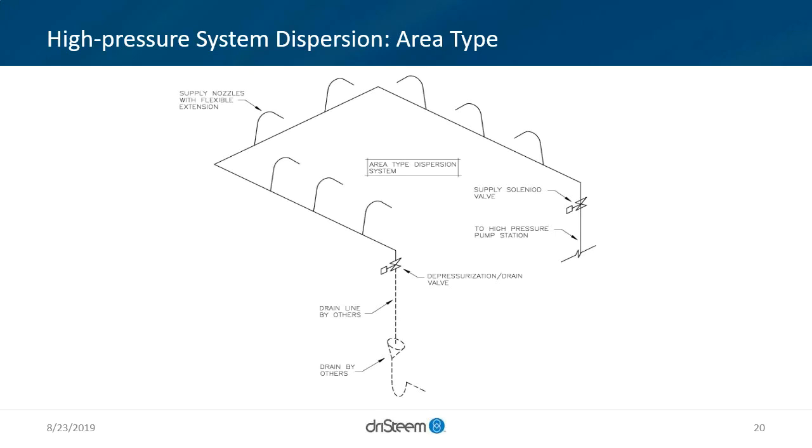The other thing is, the reason why we point it up is so air has a means to escape. If it's pointed up and the air is in that tubing, it has a way to go out that nozzle versus compressing during a shutdown cycle and essentially spitting water unatomized out of those nozzles.